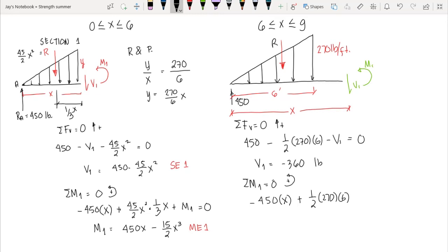And the moment arm, the distance of our resultant from the section, we know that this is 1/3 of 6. If we have 1/3 of 6, we have 2. So this is 2 meters, correct? That is the location of our resultant from point B, let's say that's B. From B, that is 2 meters.